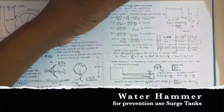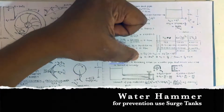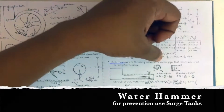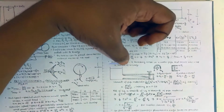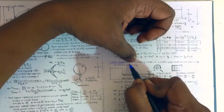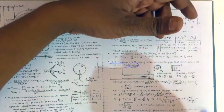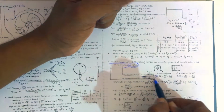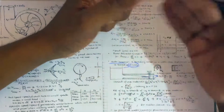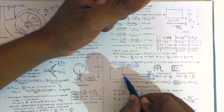In this lecture, we will study water hammer. Water hammer is a knocking noise in a water pipe that occurs when the tap is turned off briskly. Briskly means very suddenly. What happens is that water is flowing through this pipe and there is a tap there. If we close the tap, the flow of water stops abruptly.